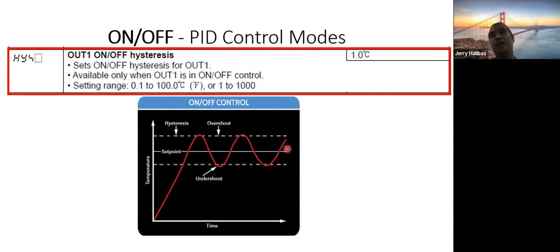So if you use PID there, it is overkill. If you're just cooling a room, people are not sensitive to a small degree difference. With the hysteresis at 1 degree, you will hardly notice 17, 18, 19. That's why it's overkill to use a PID controller for air conditioning systems in our room.